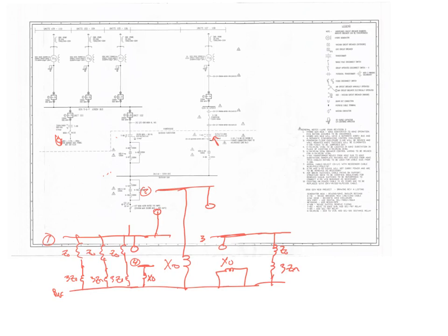Okay? Questions on that? Any questions? I missed the 3ZN part. I forgot about that. So what do you just take, I had Z, that's just the impedance of your generators. Well, isn't there an impedance associated with neutral? Is that 0? There's a transformer in there with an impedance, right? How can you make that 0? Isn't that going to limit the ground fault current? Yeah.